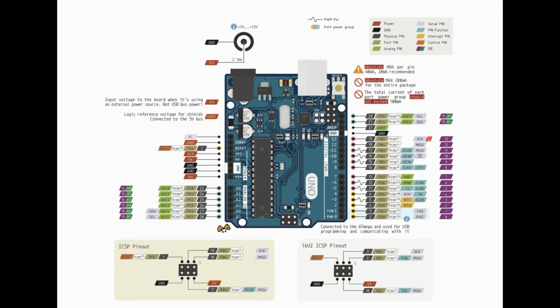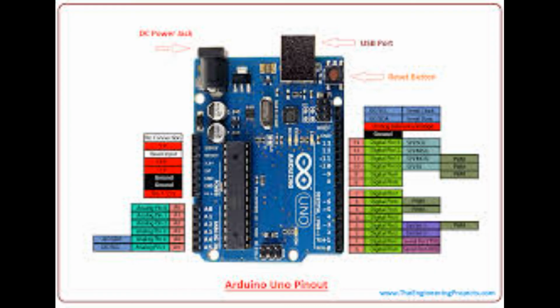Arduino Uno has a couple of other pins as explained below. AREF, used to provide reference voltage for analog inputs with the analogReference function. Reset pin, making this pin low resets the microcontroller.